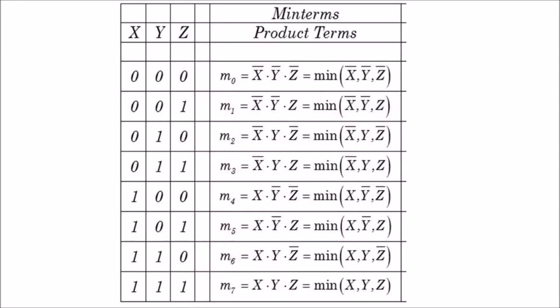So my dear students, now we are discussing the minterm values of the different variables x, y and z. Since we have three variables, the different combinations are 0 0 0, 0 0 1, 0 1 0, etc. up to 1 1 1. Let us consider the first set of variables, 0 dot 0 dot 0. As we discussed above, if the digital value is 0, we have to take the complement of that value.